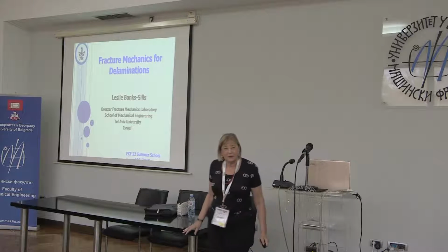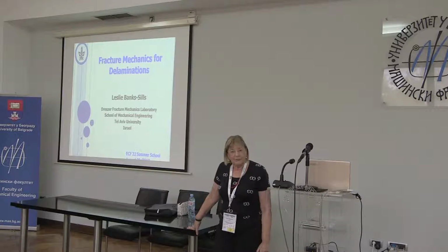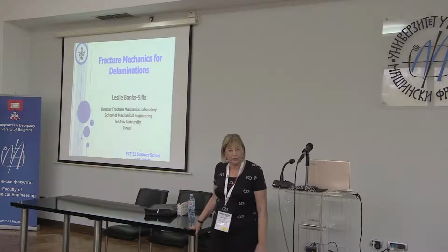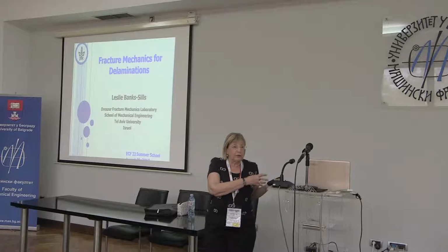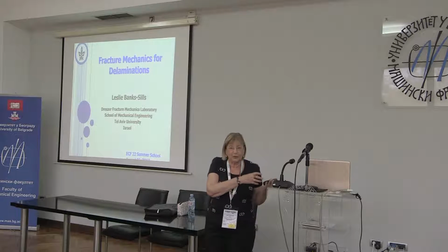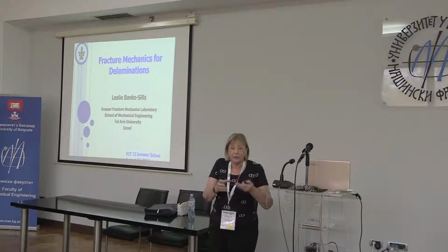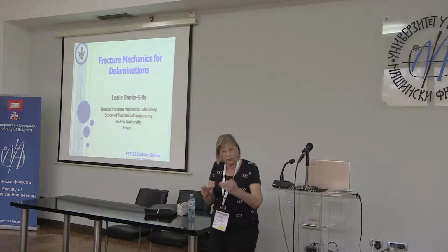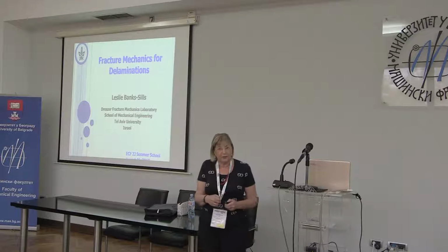Yes. I have one question about finite element analysis. You said that as the stiffness ratio goes up, then of course you will have a poorer solution. And what I was curious about is whether having a finer mesh would improve the solution. Yes, a finer mesh, and you can improve the solution. Of course, we're doing it when we know the solution, so you can see what's happening. When you don't know the solution, you have to do convergence studies and do at least 3 different meshes and see that you're getting convergence. Okay?